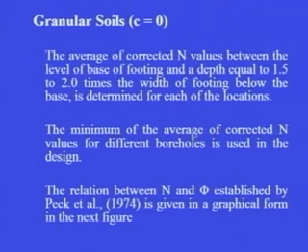So, we also call these cohesionless soils, and we find out the SPT N value at different depths, and that N value is corrected for overburden and dilatancy. Normally the corrected N values between the level of the base of the footing and a depth equal to 1.5 to 2 times the width of the footing below the base are determined for each location.